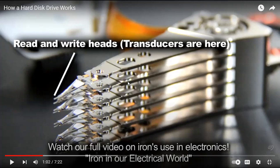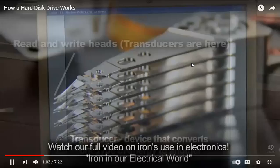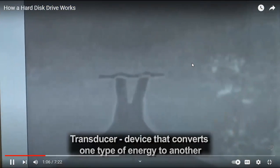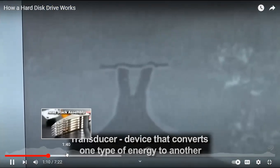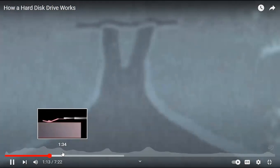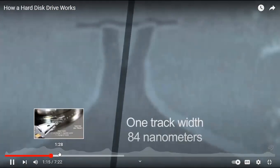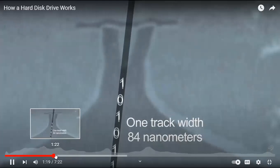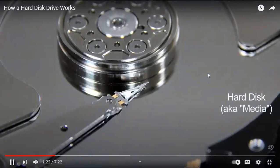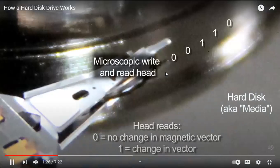So then we can use 5 platters. That means 5 magnetic disks we can use with this set of arms. Transducers on heads. This little roughly triangular shaped feature can be thought of as the size of a bit. When we write, and this is the write pole, the flux is essentially focused through that pole. The corresponding area on the media below it is magnetized.